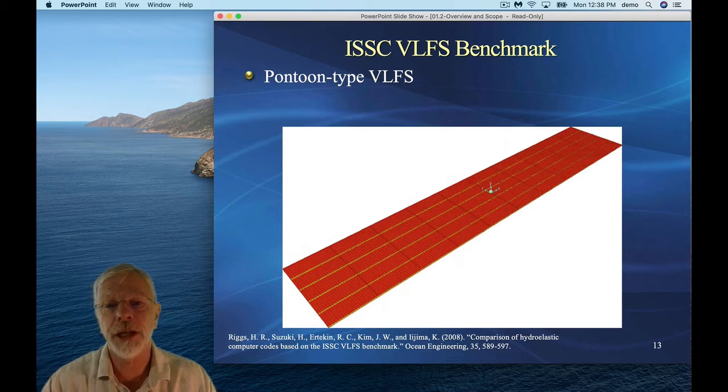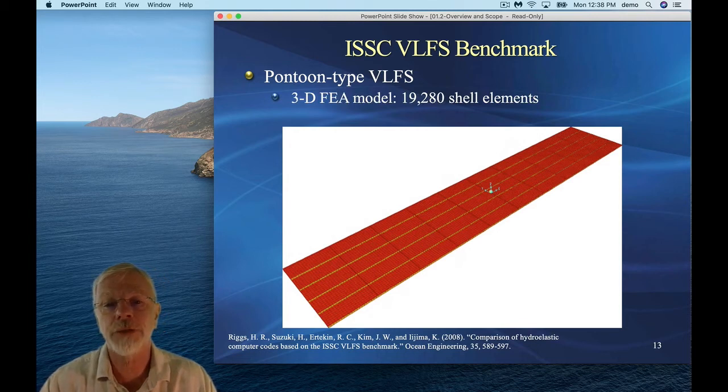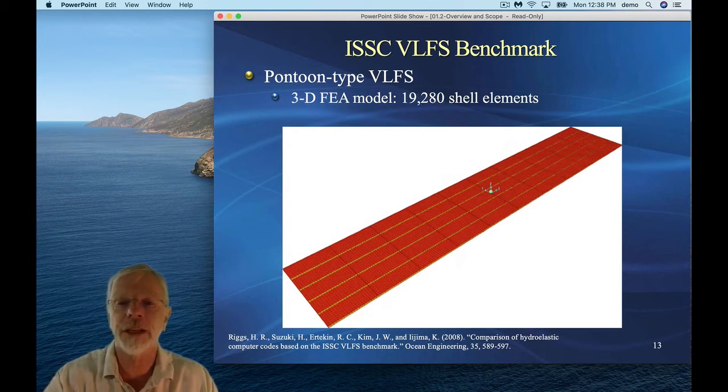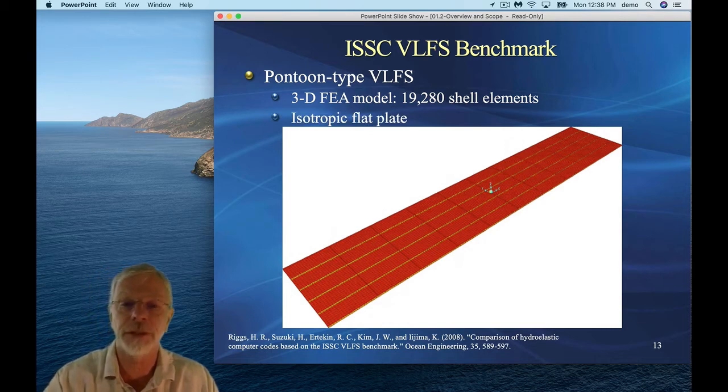Another application is pontoon type VLFS. Somewhat typical of this application would be this ISSC VLFS benchmark. Again, it's documented in the reference cited below. These pontoon type VLFSs are essentially large floating barges, potentially rectangular hull shape. The finite element model for this involved over 19,000 shell elements. Another model that can be used is an isotropic flat plate, and this is all covered in this journal publication